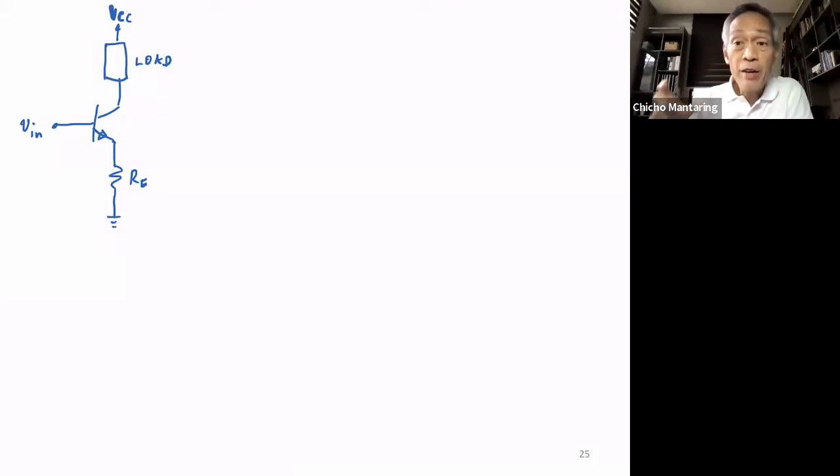If I put a voltage greater than 0.7, I'm going to burn the transistor. No? It's going to be like an invalid circuit. For example, if I put a voltage of 5 volts across my base emitter, 0.7 lang yung equivalent circuit niya, it's like an invalid circuit. Ang mangyayari in real life, masusunog yung transistor natin because there's nothing that limits the current flowing into the base. No? But if you put an emitter resistor like this, then I can now apply my input directly to the base.